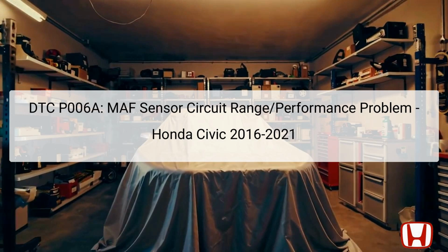If this sensor misreads or fails, it can lead to various performance issues. In this particular case, you may also see associated codes such as P2228 or P2229, which need to be addressed prior to focusing on the P006A. Always begin troubleshooting with a thorough inspection of the related systems, ensuring that all components are functioning correctly before diving